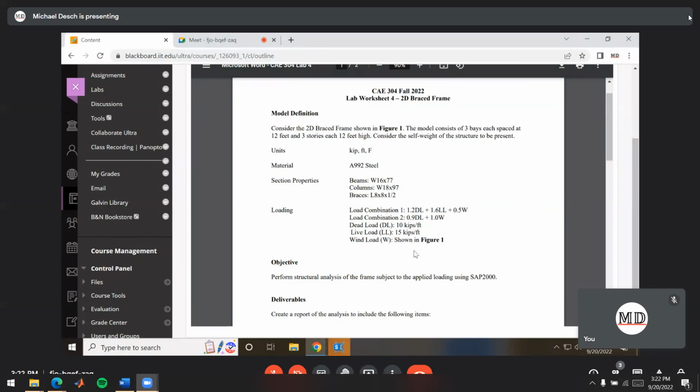And then we've also got other types of loads throughout the building, like wind loads, seismic loads, snow loads, rain ponding loads. There's loads from the earth if it's bearing against the building, like on the footings or on the foundation walls. It's called lateral earth pressure. If you're building a dam or something, that's called hydrostatic pressure. I'm sure you'll know about that from fluids, I hope. So there's all sorts of different types of loads acting on our building.